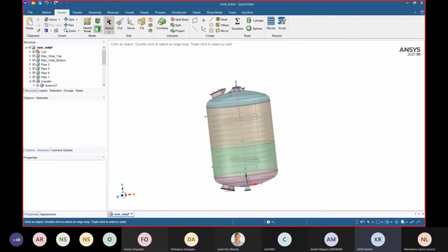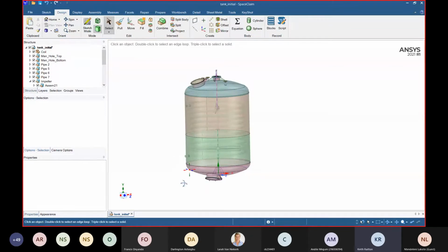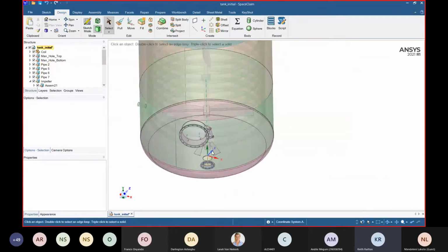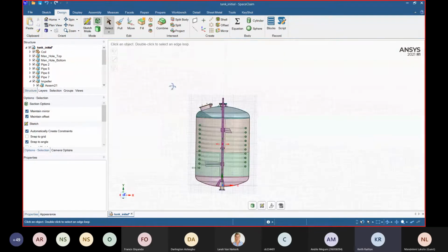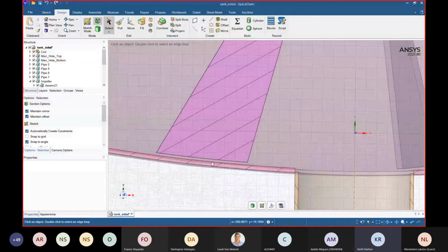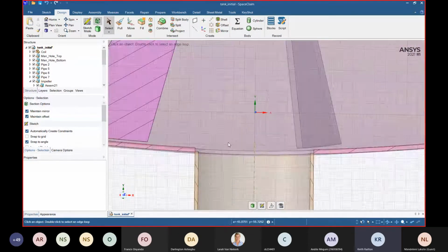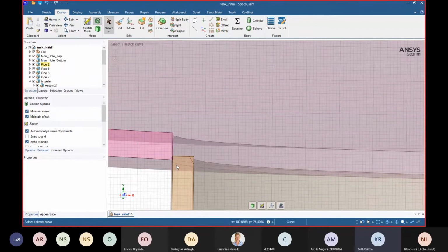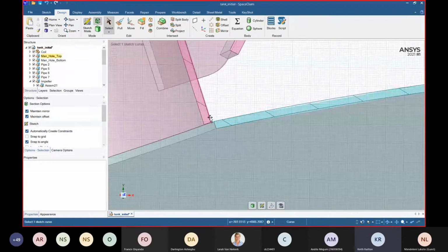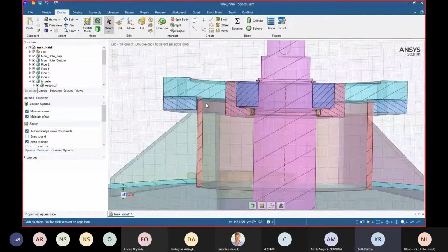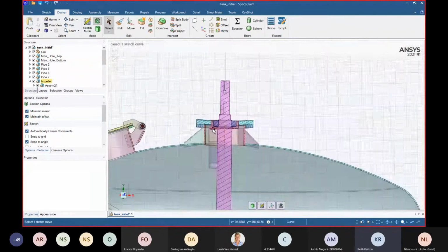Okay, so I've done the impeller, I'm happy with the impeller, and I've removed all the different sections. Now I need to look for holes and anything else. So I'm going to check a cross section and see what my geometry looks like. Okay, there are a couple of things I can notice. There's a small gap there. These aren't really lined up nicely, so it's going to create a little bit of issues. We can align those. And let's look up here. There are also issues here. And lastly, there's probably going to be a leak here, so we can simplify that area.